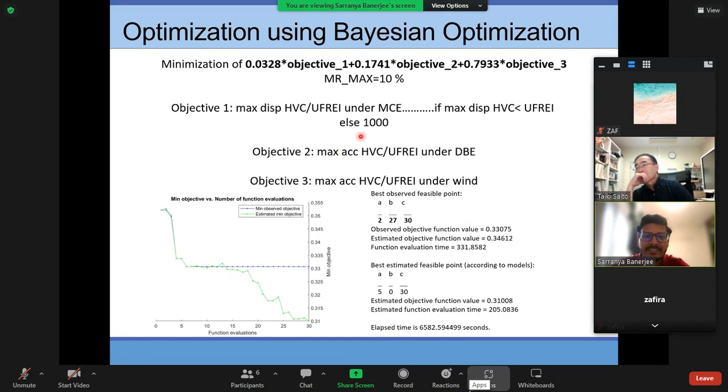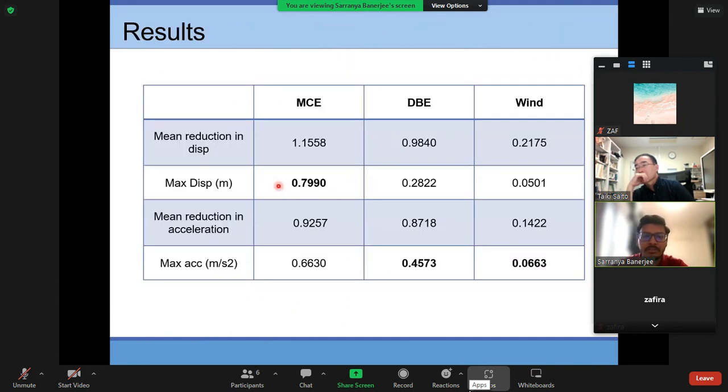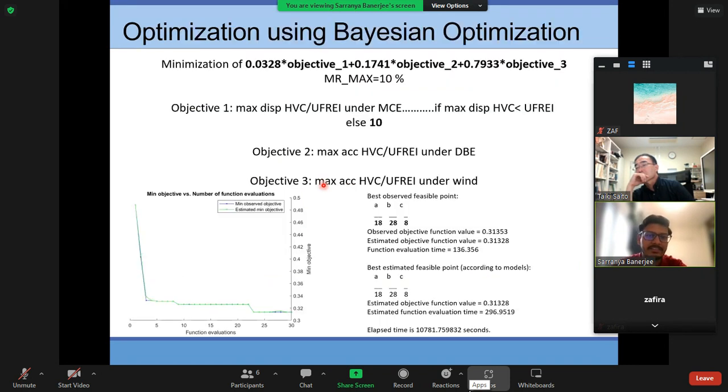So what I did next is I reduced this large value to a comparatively smaller value, say 10. These are the results with the large value. Again, we see here that the displacement has now reduced from the unbonded isolator case. Now I have taken it as 10. By using 10, I see that the results are converging very nicely, and I am also getting the required kind of performance from my hybrid controller.